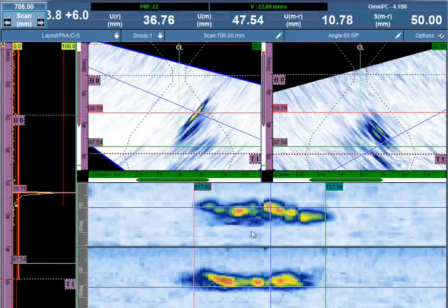And again, shear wave tip diffraction, most beneficial on crack type indication where the ligaments are smaller than the beam size. Amplitude drop where there is favorable orientation. Near perpendicular, typical of weld bevel flaws such as lack of fusion.